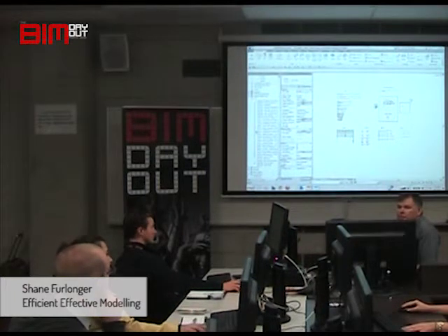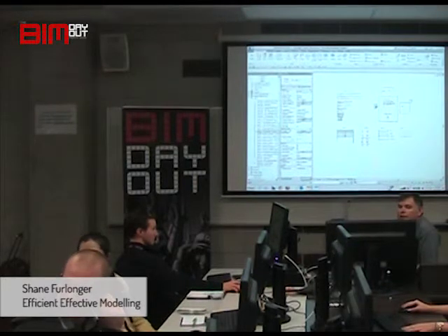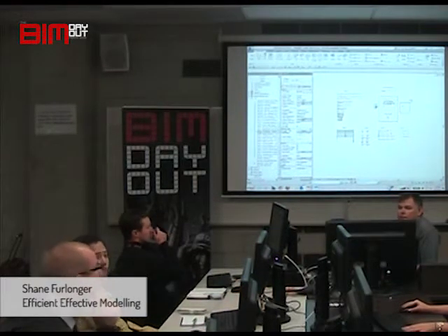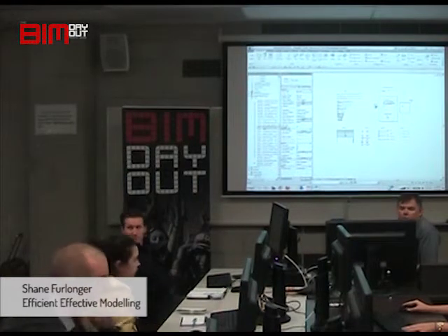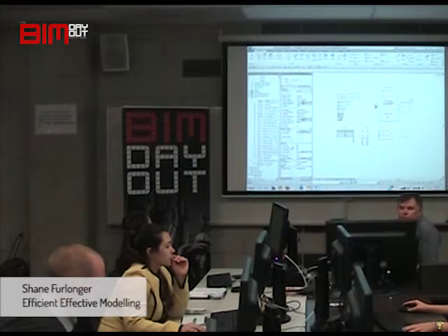Absolutely. And once you've got your template set up, you can always transfer project standards to other projects, so that upgrading the project is free. So just use Transfer Project Standards from your Manage menu.